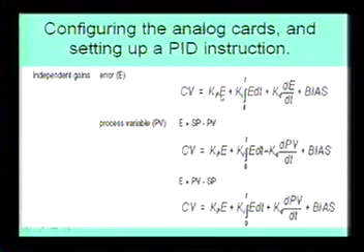So you can have a fully proportional controller, and it's real simple. All you do is say, okay, I want a proportional controller, and you just set I and D to 0, and you've got a proportional controller. Now you can say, well, gosh, why do I need a PID for this routine? And you're right, you could actually mathematically solve this and create a ramp up type deal. But the PID is so easy to use that it just makes sense to use it. Now, if you wanted a PI controller, you would just set your D, your derivative, to 0. So you get the idea how this actually works.